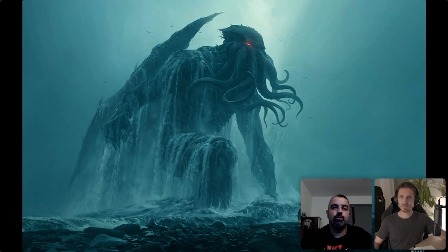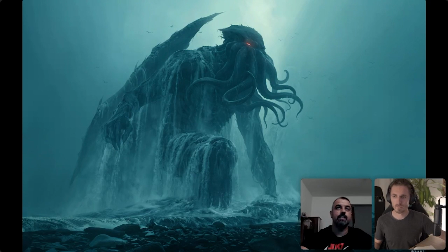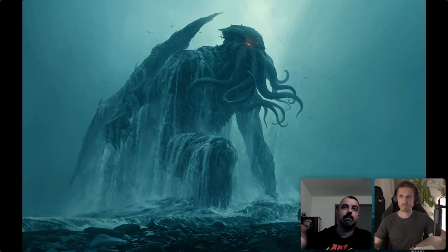Sometimes you can mask the particles that you don't want to mesh, maybe with the surface field distance, so only the bigger chunks of water get meshed, but the small ones you can isolate, mesh with a smaller scale for higher-res details, or just delete them or render them as white water. I will show some previews with different droplets. I hope this answered his question. Hope so.